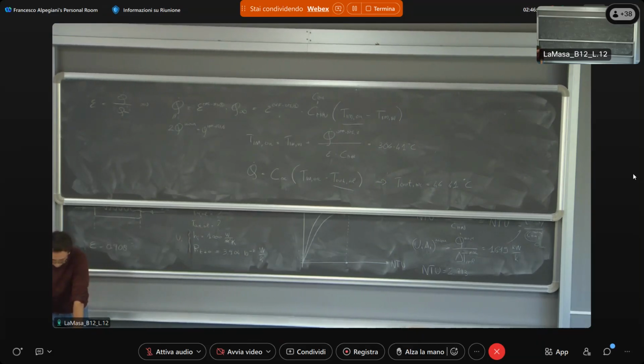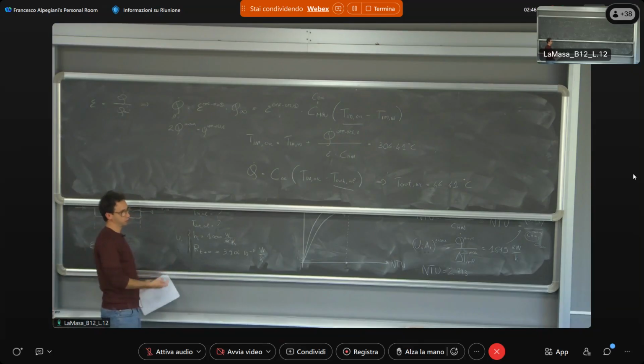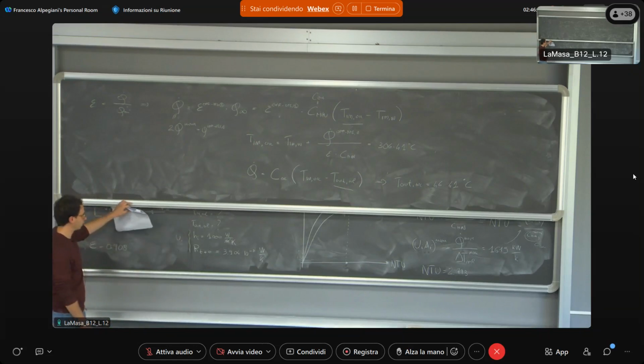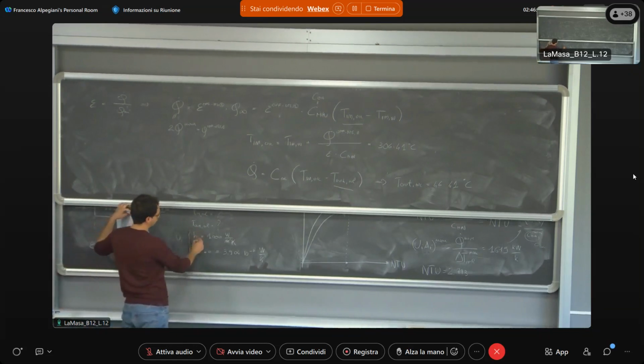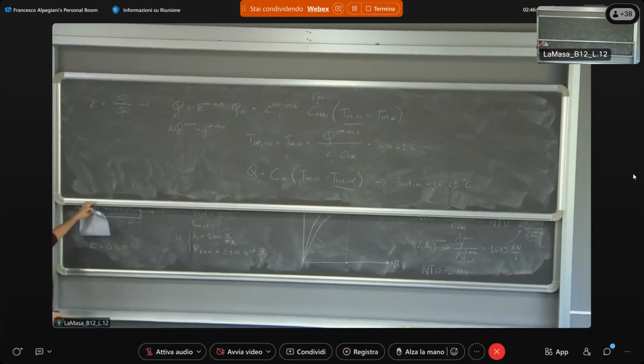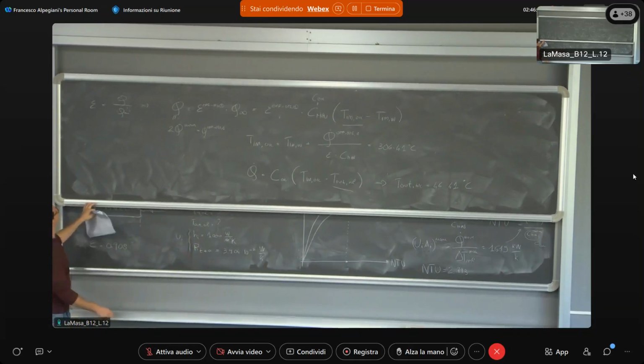water with the temperature. Okay, so in this case we are talking about another off-design condition in which we cannot anymore consider that U remains the same because we have a variation in the heat transfer coefficient of the water due to the change in velocity inside the tube. And so we can write that